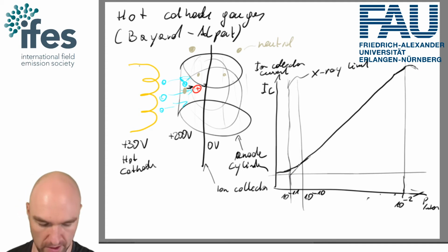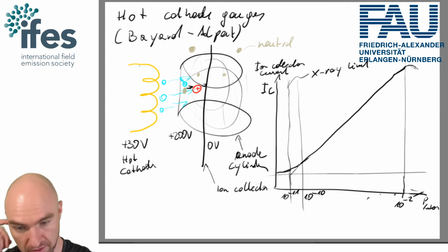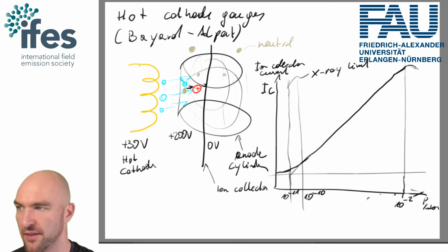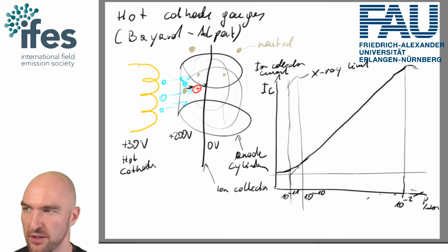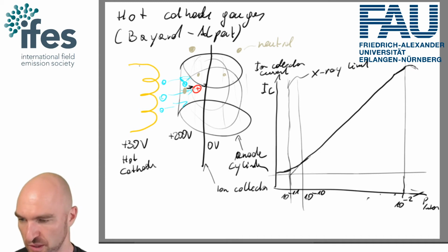And this makes it pretty well suited for measurement for atom probe or any other ultra high vacuum system where you don't have anything that produces too many contaminants. So if you periodically put gases in, hydrocarbons and stuff like that would crack at the hot cathode, it's probably not a good idea to use one of those gauges, but we don't usually do that.